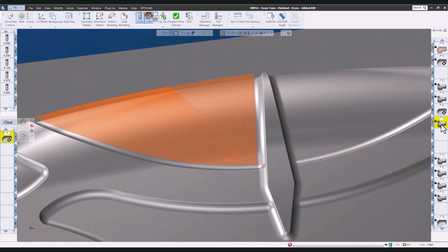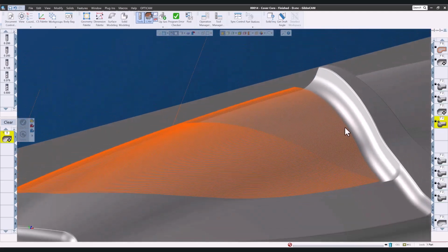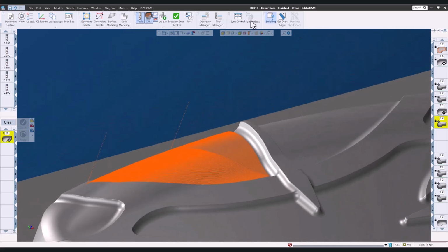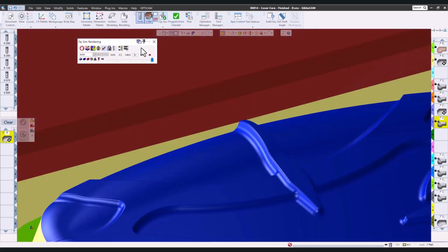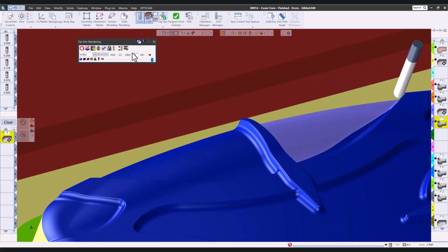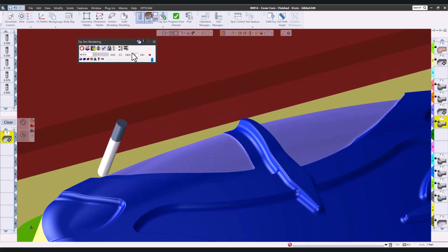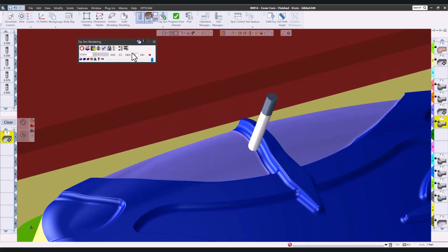For the one on the back left, I selected the parallel to curves based on a geodesic mesh. The same logic as the first 2, but based on a geodesic mesh rather than surfaces. You can see how smooth and consistent this toolpath is. And let's see those 2 running. This one is running nicely, but you can see that every stroke goes to that back right corner, making toolpath much more dense in that area. While this one is conforming to the closed sides of the pocket, and every step over is consistent.